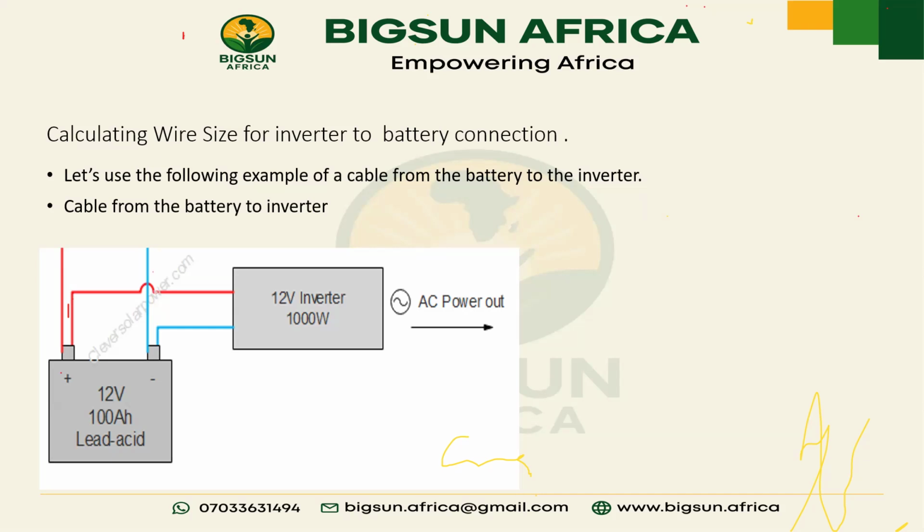So let's look at cable size, calculating wire size for inverter to battery. Before we continue with this, I want to say that on standard condition, the standard distance between your inverter and your battery should not be more than 3 meters.